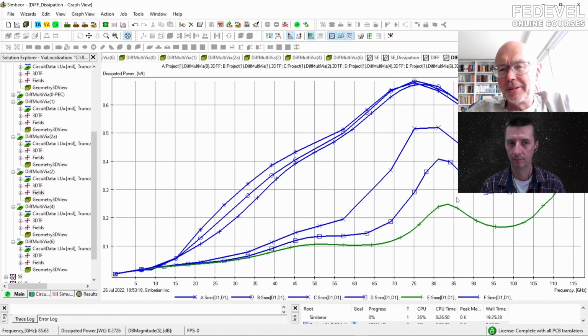And in a differential line, the signal travels in this wave guiding structure as differential and common mode, or as even and odd mode, let's say, to be more precise. So even mode or common mode is undesirable, but you'll have it if you turn traces, and inevitably you have to go through some turns, and you'll get some transformations, and then you have to predict those.